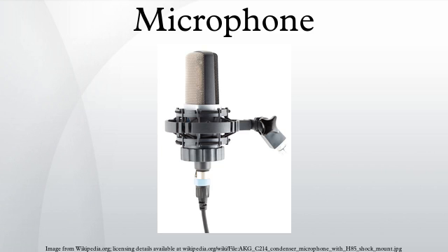Stereophonic microphones use the same connector. There is no obvious way to determine which standard is used by equipment and microphones. Only the best electret microphones rival good DC-polarized units in terms of noise level and quality. Electret microphones lend themselves to inexpensive mass production, while inherently expensive non-electret condenser microphones are made to higher quality.